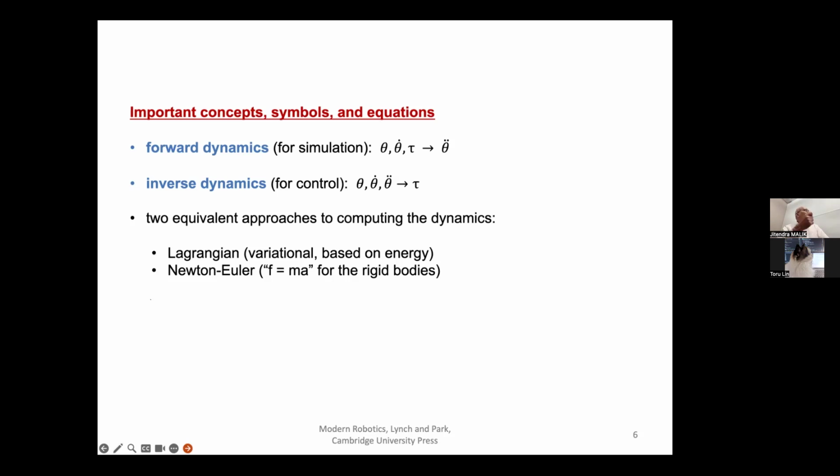And again, for dynamics, there are classic ways of doing it. I mean, F equals ma, the Newton method, which you can integrate in time. This is what you learned in high school or freshman physics. And then there's a fancier way, which is the Lagrangian dynamics. The difference between them is essentially when you have multiple degrees of freedom and the motion is constrained in some way, then the Lagrangian formulation is more convenient because it's in terms of the true degrees of freedom of the system.